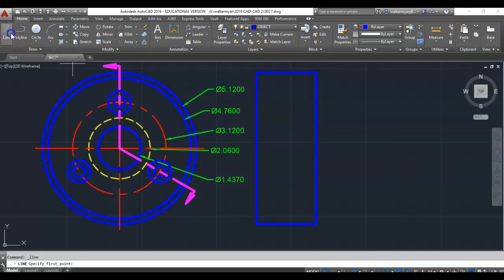Alright, now I'm going to bring the top of the hidden circle over. That's going to stick out 1 inch. Got 1 inch, connect up. The wall where the 2 pieces meet is going to be 0.62 thick, so I'll use offset 0.62, and then I will trim that line there.